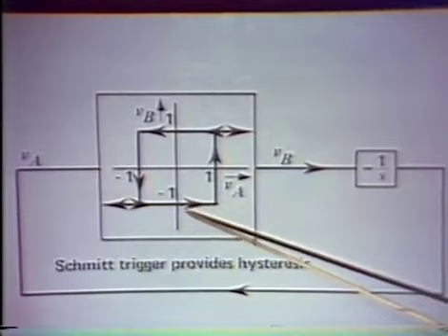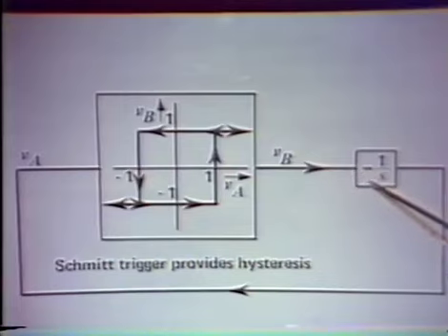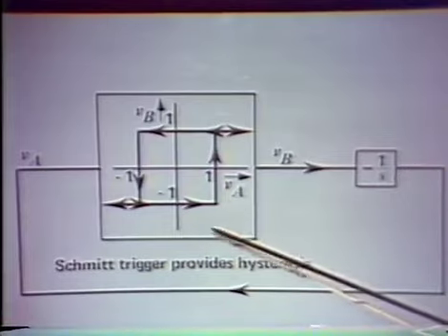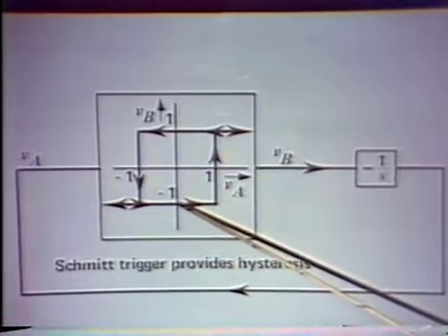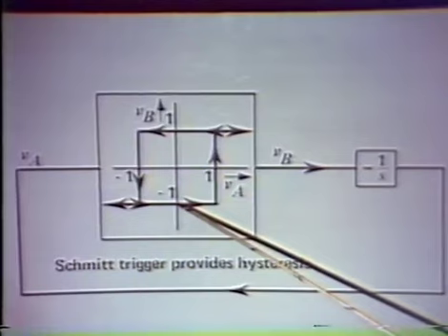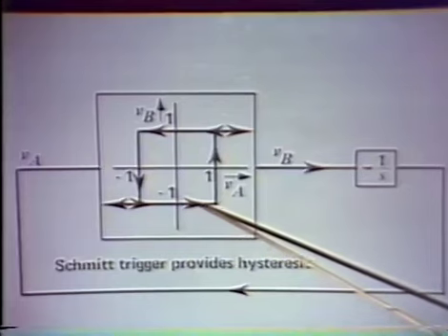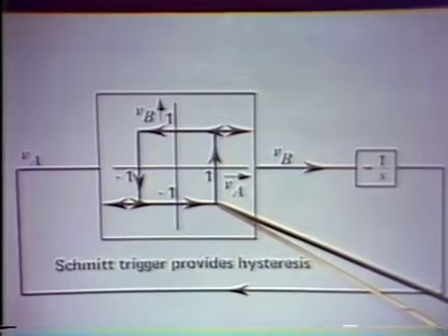We have a -1 volt applied to the integrator. Consequently, since the integrator includes an inversion, the output of the integrator would change in a positive direction. So we walk along the characteristics starting at this point with the output of the integrator 0, its input -1 volt. We'd integrate the negative of that, walk along the characteristics to this point.